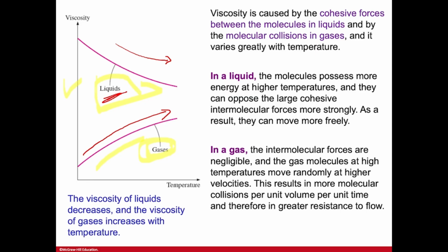So let's say you're talking about a re-entry vehicle: as soon as it enters, there's so much friction and it comes at such high velocities, even Mach 20, Mach 25 speeds, that it gets really hot, right? So the temperature on the surface increases. So there the viscosity of that atmosphere, even though it's a very thin rarefied atmosphere, increases dramatically because the temperature is higher, and as a result you see more friction and more heat and drag effects.